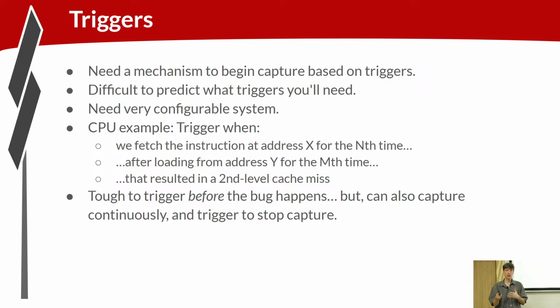You're debugging a particular issue that relates to memory. You go in and you configure the triggers to be based on some memory event, and then you use that to capture. You get your data, whatever you can manage to capture, use that to narrow in on the bug a little bit more, refine the triggers to try to catch something else.